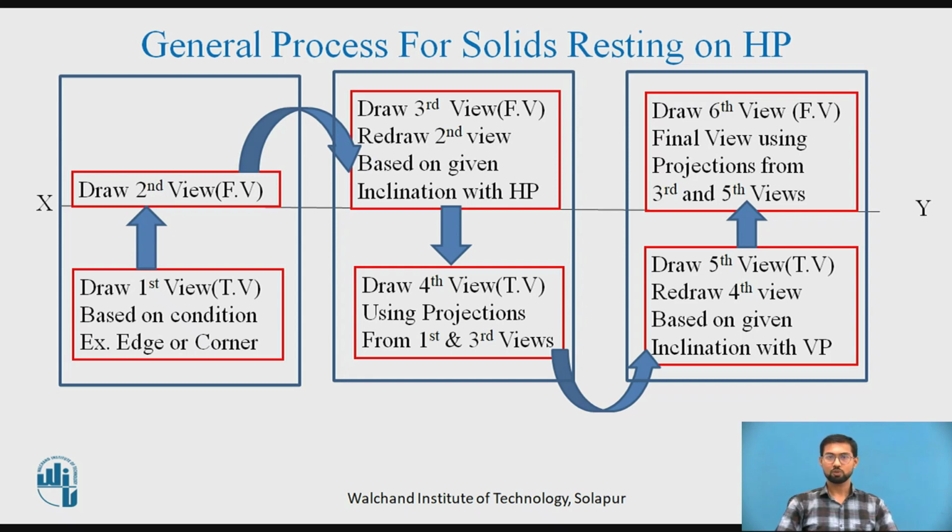But before going to solve this example, remember the general process which is followed for solids resting on HP. In this process, first we draw a top view based on the condition, whether it is resting on an edge or corner or face. Then we draw its front view above the XY line. Then for the third view, we redraw the second view based on the given inclination with HP. Then we move ahead with the top view.